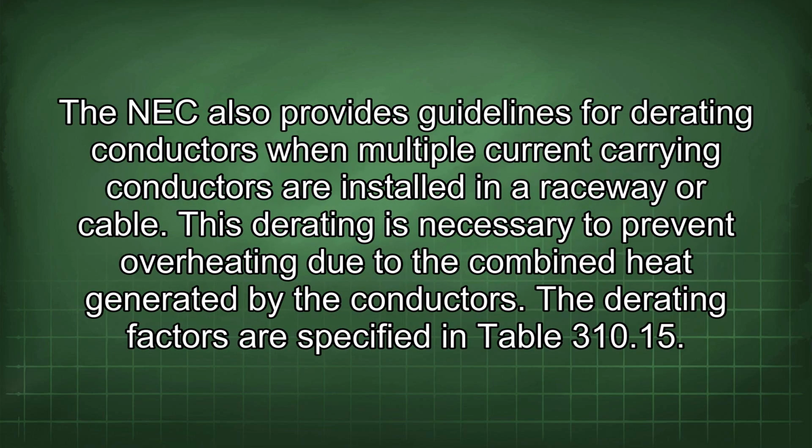The NEC also provides guidelines for derating conductors when multiple current-carrying conductors are installed in a raceway or cable. This derating is necessary to prevent overheating due to the combined heat generated by the conductors. The derating factors are specified in Table 310.15(C)(1).